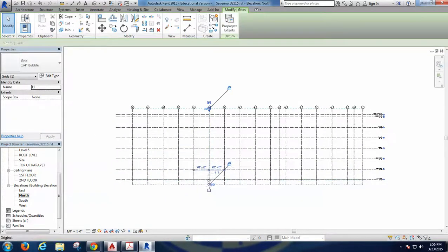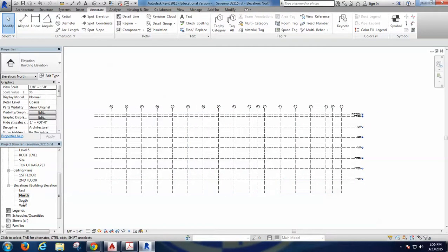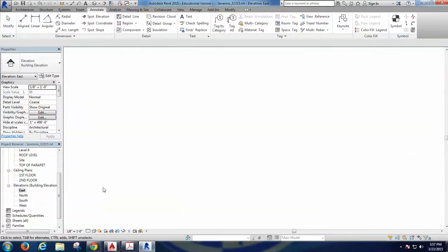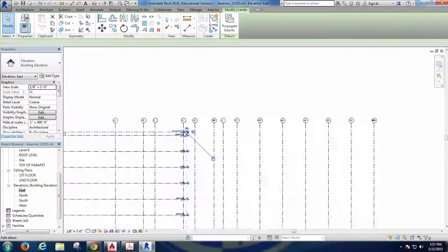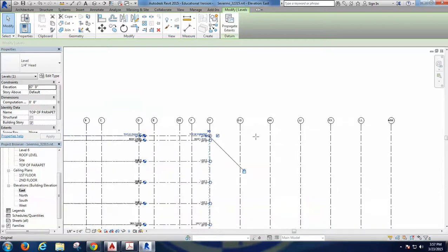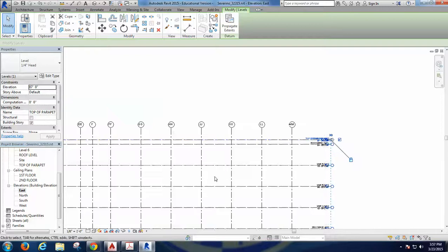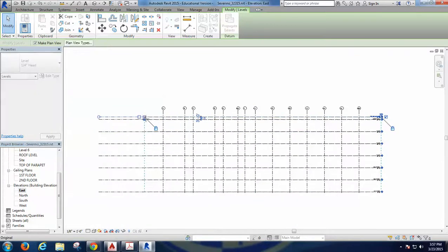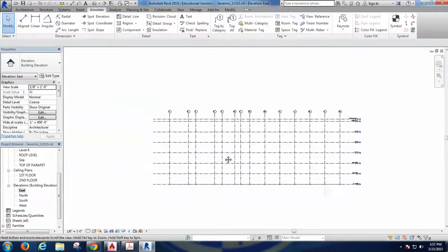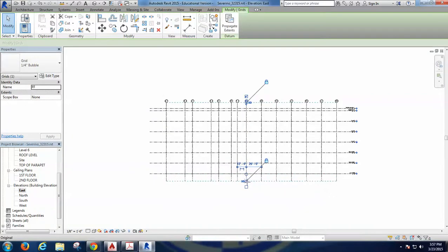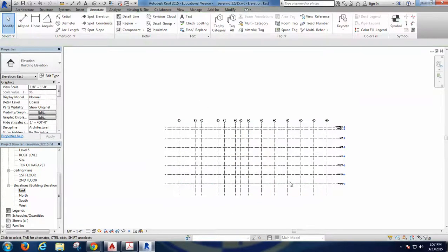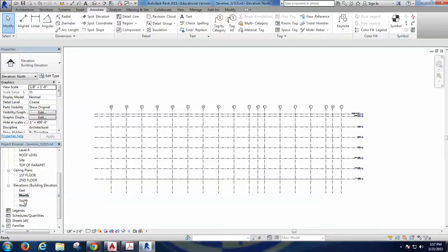The grid should expand a little bit further down. We're going to have a basement plan nevertheless, and you should do that in both north and south, which are the same, and east and west. You see how this is totally different. So you select the circle there and you expand them so you make sure you're crossing all the grids, and again extending beyond the grids the same amount. Select the grids, taking them down. Okay, this is a proper elevation of levels and grids at this point.